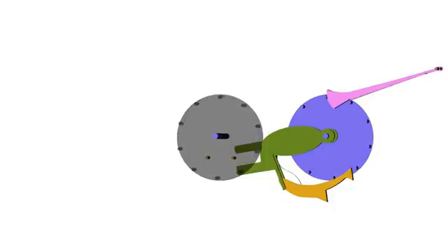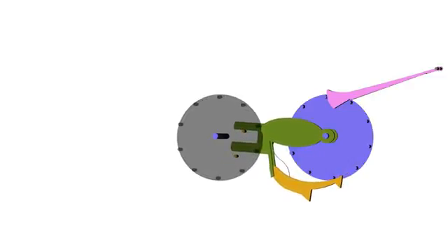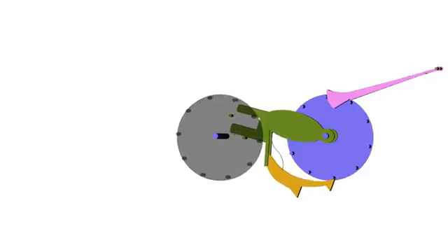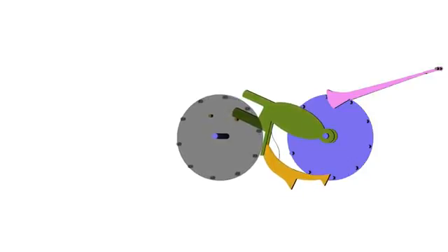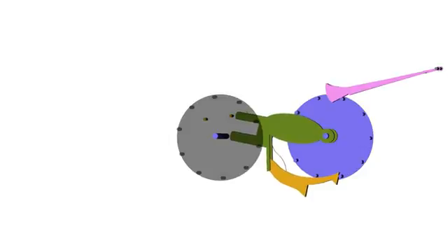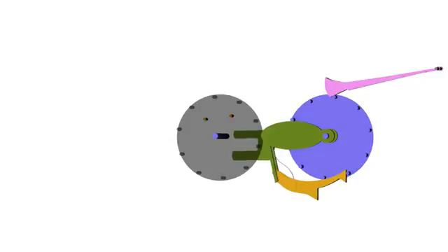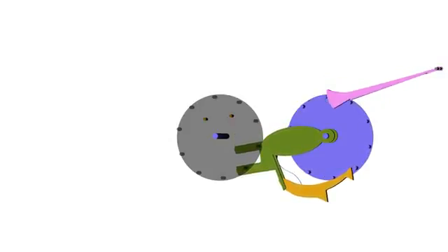As the carry lever rises upwards, the carry pawl also rises, and its spring causes it to maintain contact with the pins on the face of the higher order accumulator. When the lower order accumulator advances from 9 to 0, the heavily weighted carry lever falls back to its resting place with enough force to cause the spring-loaded pawl to engage the higher order accumulator and advance it by 1 digit. The carry operation is shown here in slow motion. In the actual machine, the carry operation happens almost instantaneously.